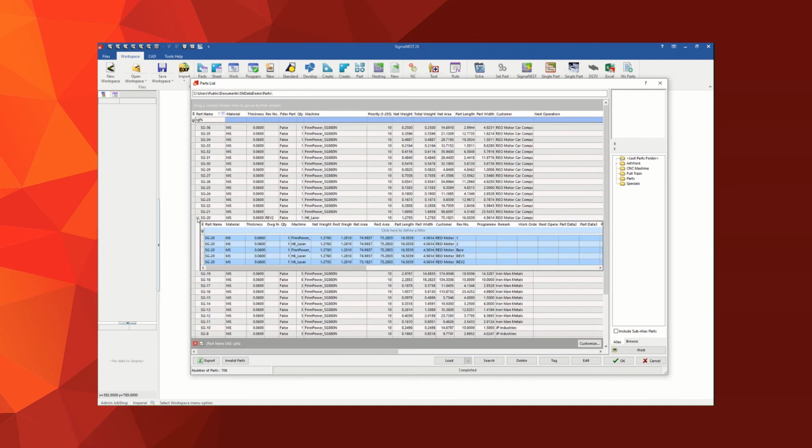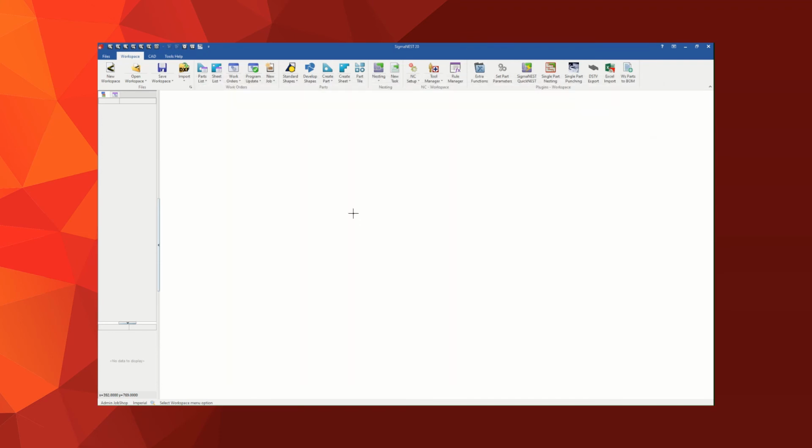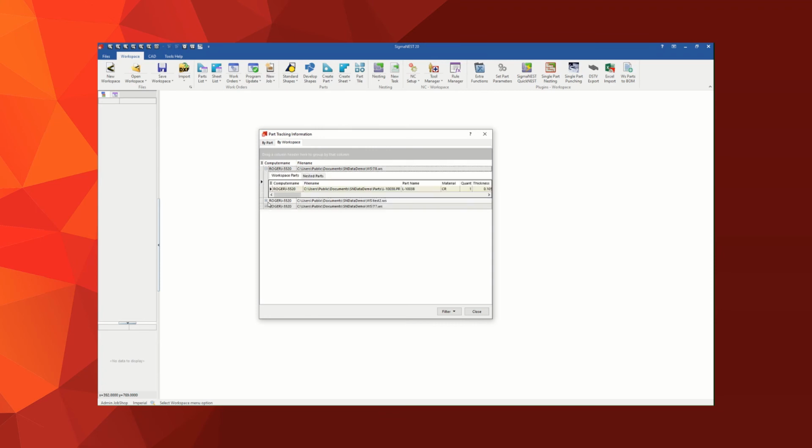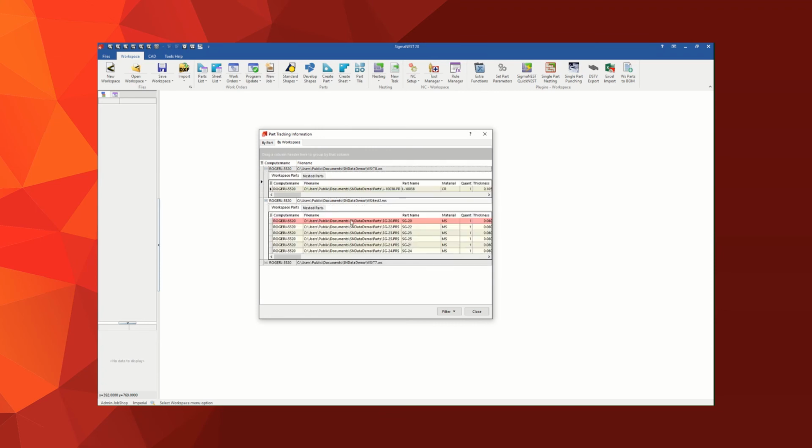And I can see that there is a drop down, so we definitely know that there are some other parts. I got revision numbers 1, 2, base, Rev 1, and Rev 2. So this is definitely a prime suspect for workspaces that need to be updated. So now I can actually go into my drop down list and hit my part tracking item. And inside of here, I'm just going to be looking for different workspaces with parts in them that have turned red. That's going to throw me a little red flag stating that there's been an issue, like right here. So I can see that this part currently has an updated version or a more up-to-date version. So I can go ahead and get that taken care of.